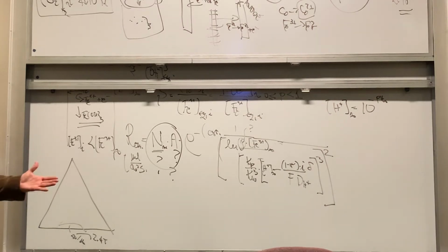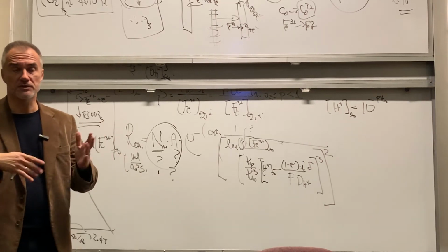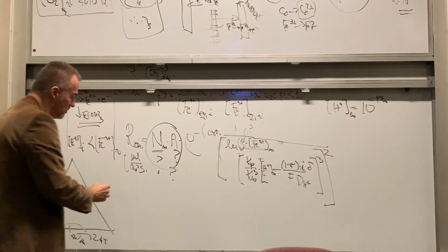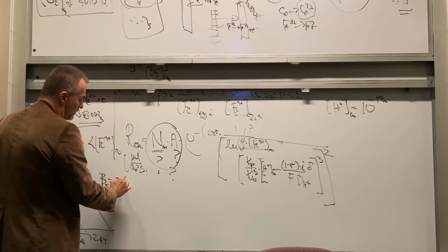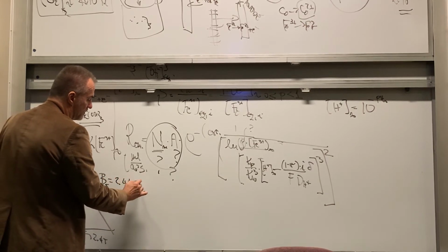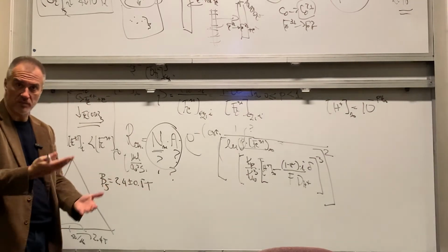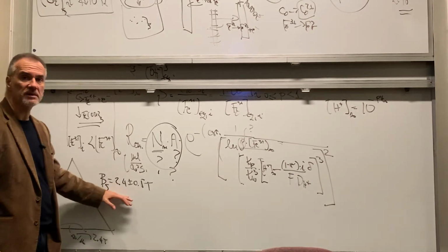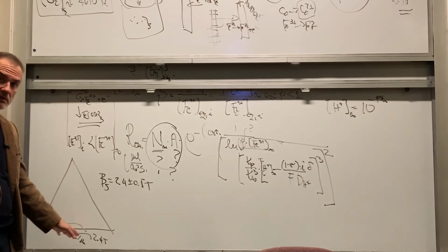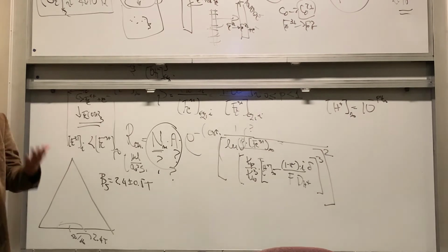Then if I have no oxide phase, for a reasonably accurate measurement of the volume, the dimensions of the film, and magnetization from the looper measurements, etc., I should get probably B sub S, if it's a pure film, 2.4 plus minus 0.5 Teslas. Yeah, this is the error bar that I'm making, because the estimate of the volume is not always spectacular and so on, right? But this is what you get if I measure the saturation magnetic moment of these alloys with no oxide phase. However,